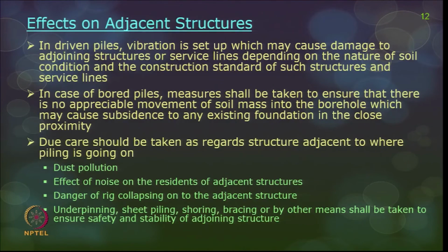Effects on adjacent structures: when you are doing the pile driving operation, sometimes the vibration or even the blow can create a lot of hazards to the neighboring structures, starting from dust, starting from noise. So, all these PPEs the workers have to wear, and you have to barricade the structure completely, especially when you are doing the piling operation. In driven piles, vibration is set up which may cause damage to adjoining structures or even service lines, depending on the nature of soil condition and the construction standard of such structures and service lines.